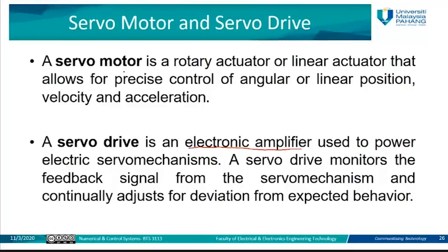Which one requires an interpolator? The continuous path system. Okay, continuous path system. So an interpolator is required for continuous path. Why do we need to use it? Because it's like a closed loop. It needs to continue after a process. Okay, the machine is required to perform a task during the motion. Yes. Okay. Thank you.